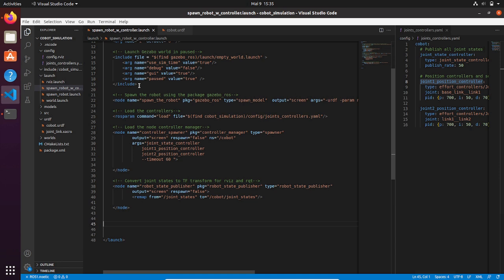In ROS there exists a very user-friendly GUI that you can use in your simulation, and allows you to test very easily how each joint behaves to a certain command in joint position.